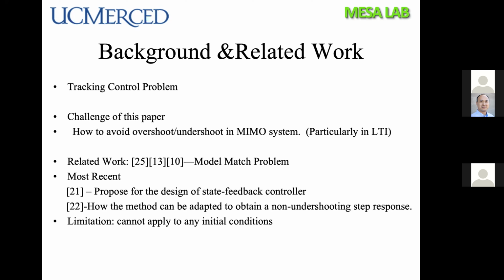Only a small number of the closed loop system modes appear in each component of the tracking error, which is defined as the difference between the system output and the desired target value. Indeed, the closed loop eigenstructure can be constrained in such a way that each component of the tracking error is driven only by a single real valued closed loop mode, which is exponential in the form e to the power of lambda t in continuous time.